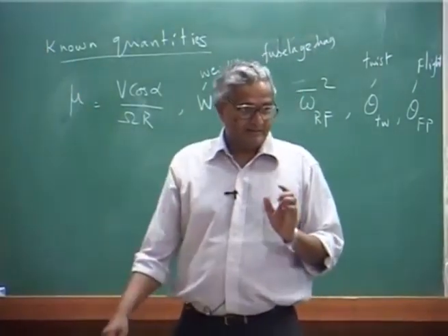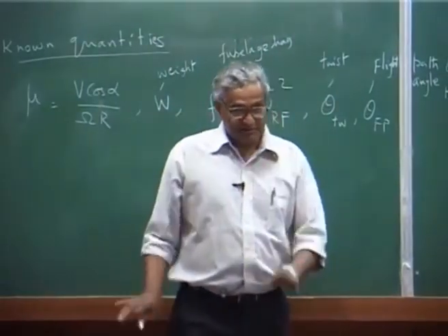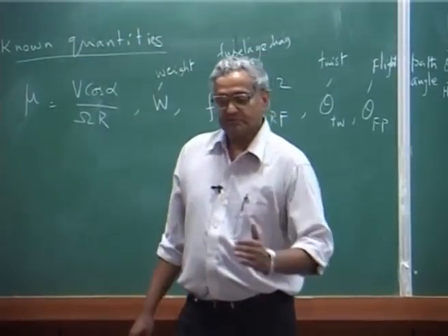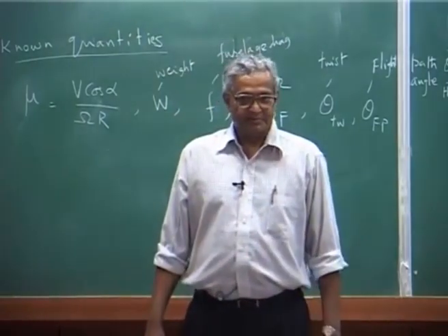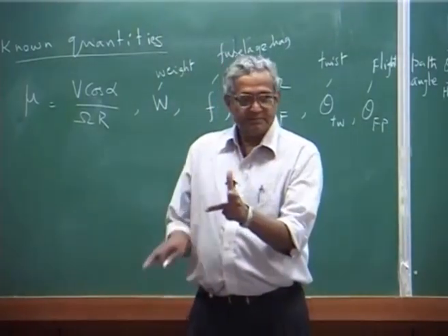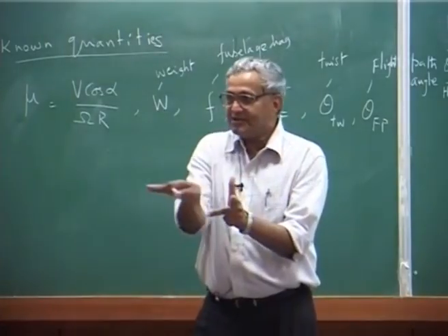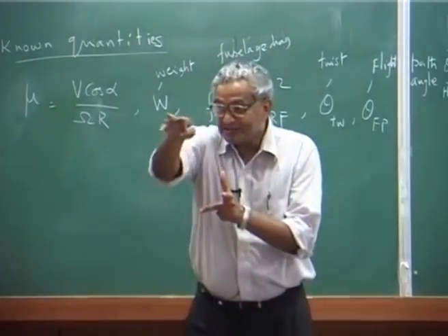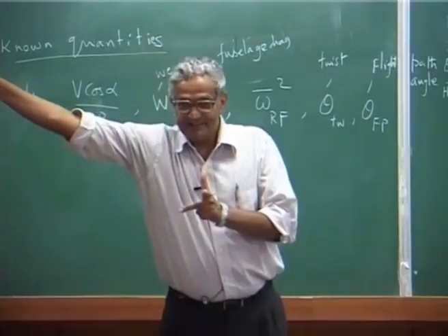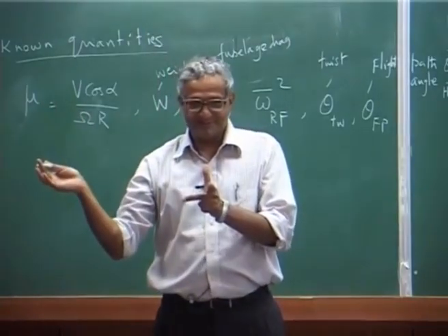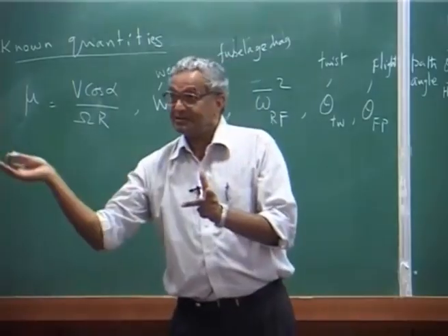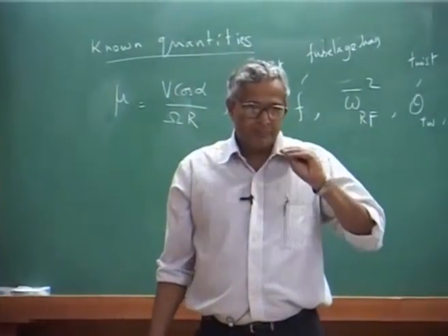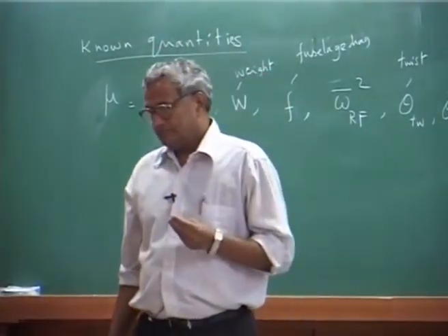Okay. Then you may have to say what the yaw is also, because the heading can be something like this. If it is making a maneuver, the earth is a fixed coordinate system, but the helicopter heading can change, you follow. On the other hand, you can say my heading of the helicopter is the same, but my velocity vector is this way, then you have a side slip, you follow, because you are also moving sideways. So, all these flight conditions become a little complicated.